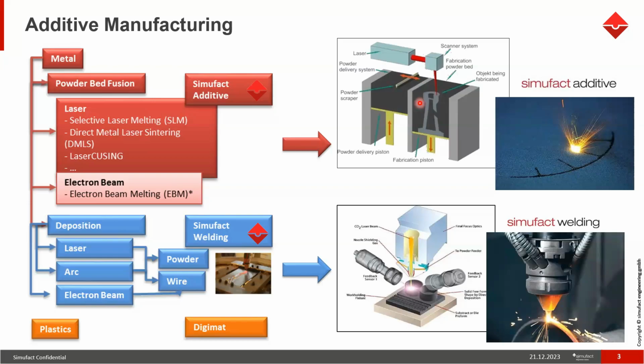If you take 100 height of this particular component, there will be around 100 to 150 layers of slicing done by the software. And each slice will be there like this. The machine will read each slice, then the powder will be laid on this. The laser will melt that region according to the information that we are giving to the machine. And then the part gets manufactured in this fashion.